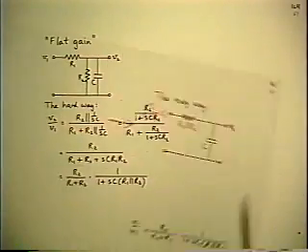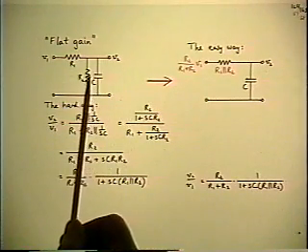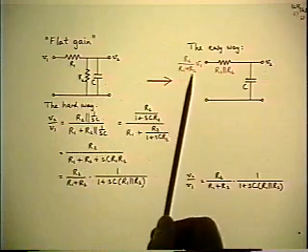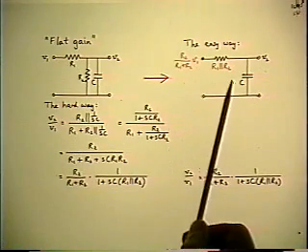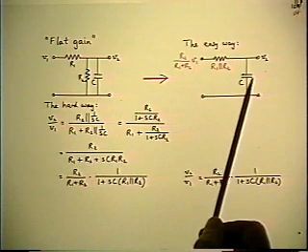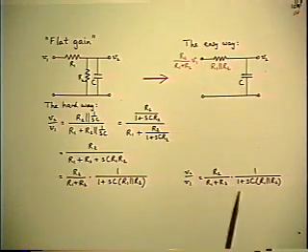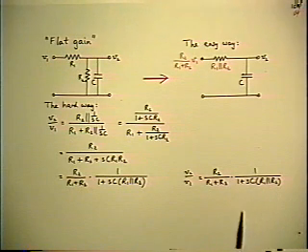Well, it took about 4 lines of algebra to get there, and it was plain dog work just to get the algebra. So here's the easy way to do it. Use Thevenin's theorem to absorb the R1 and R2 into an equivalent, which reduces it from a 2-loop circuit to a single-loop circuit. Write the answer as a voltage divider, and there's the answer in one line.